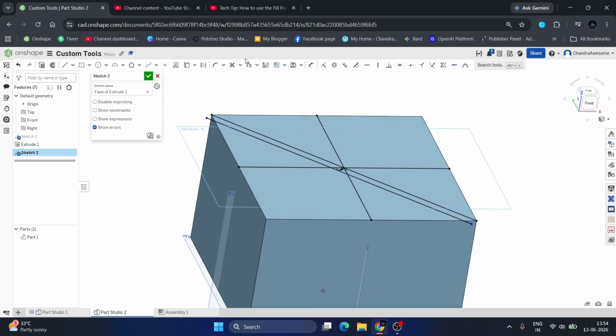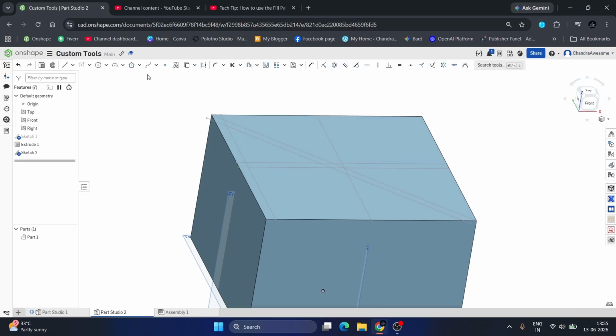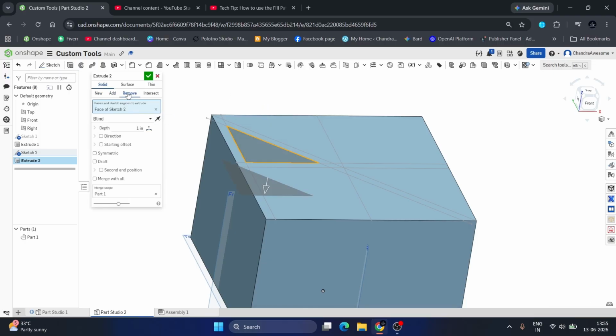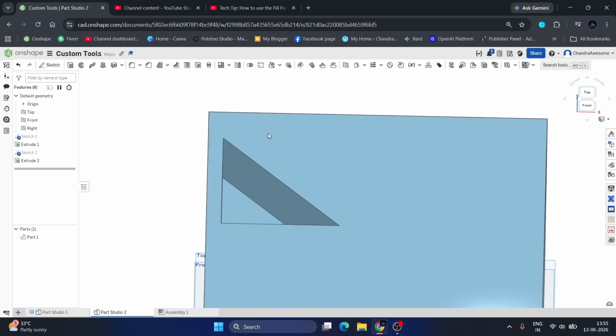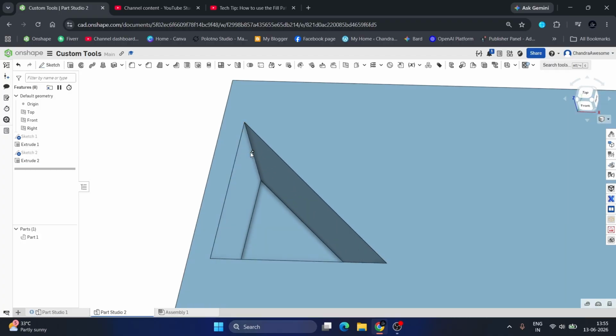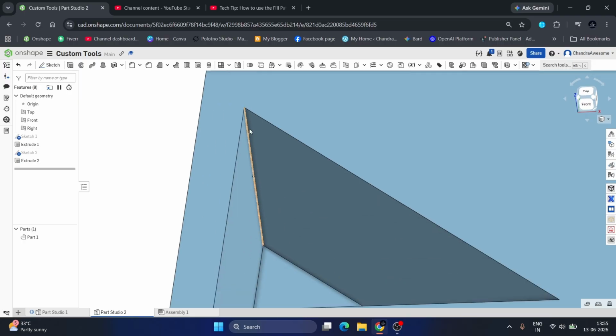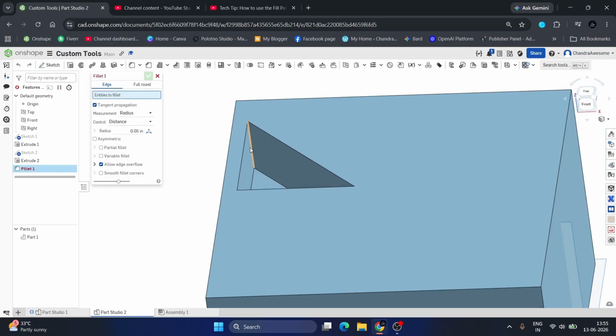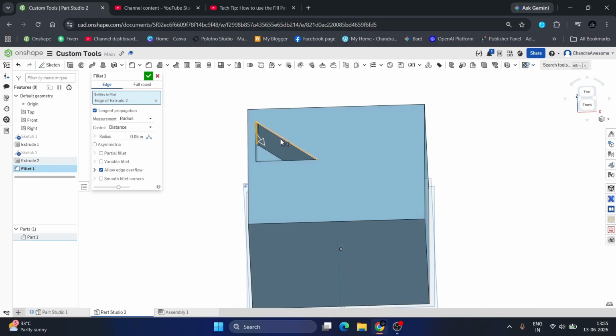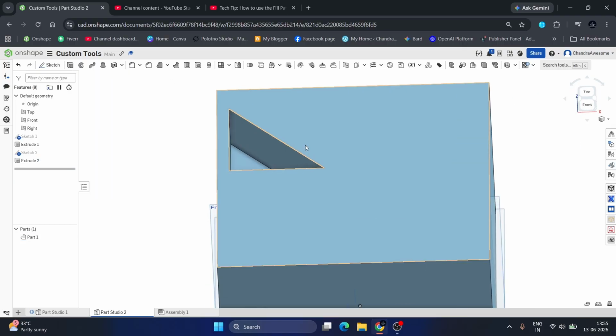I just simply select it, select the other offset again. It should be in the opposite direction. Click OK. Now select offset again. Double click to save it and click enter. So this is the region I want. I just need to simply select it, click on extrude and remove. Okay, and this is the process. And if I want to smooth these corners, I need to use the fillet tool once again to smooth these gaps. So this is the traditional approach that we have used to follow.